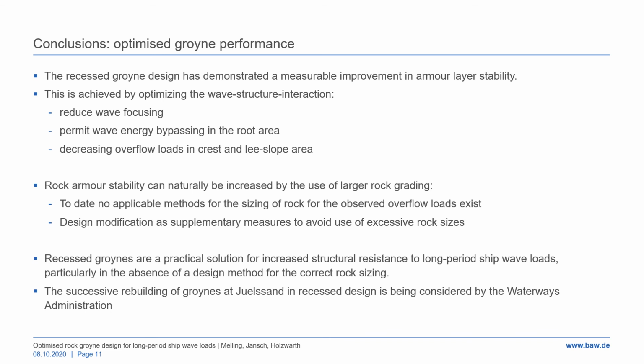Naturally, rock armour stability can also be increased by simply the use of a larger rock grading. However, to date, no applicable methods exist for the sizing of rock for the observed overflow loads. Also, design modifications can be seen as supplementary measures to avoid the use of excessive rock sizes. So we find that recessed groynes are a practical solution for the increased structural resistance to long-period shipwave loads, particularly in the absence of a design method for the correct rock sizing. The successive rebuilding of groynes at Ulsand in the recessed design is currently being considered.